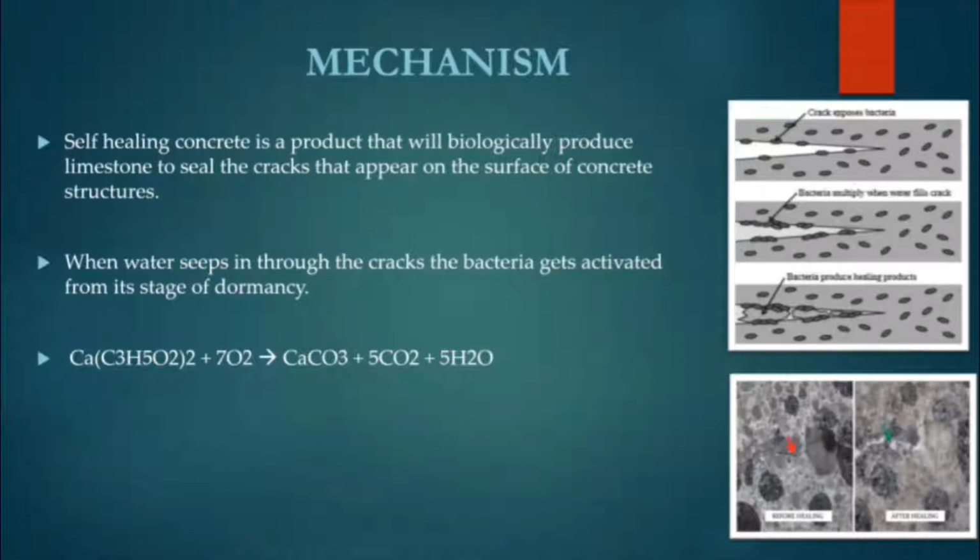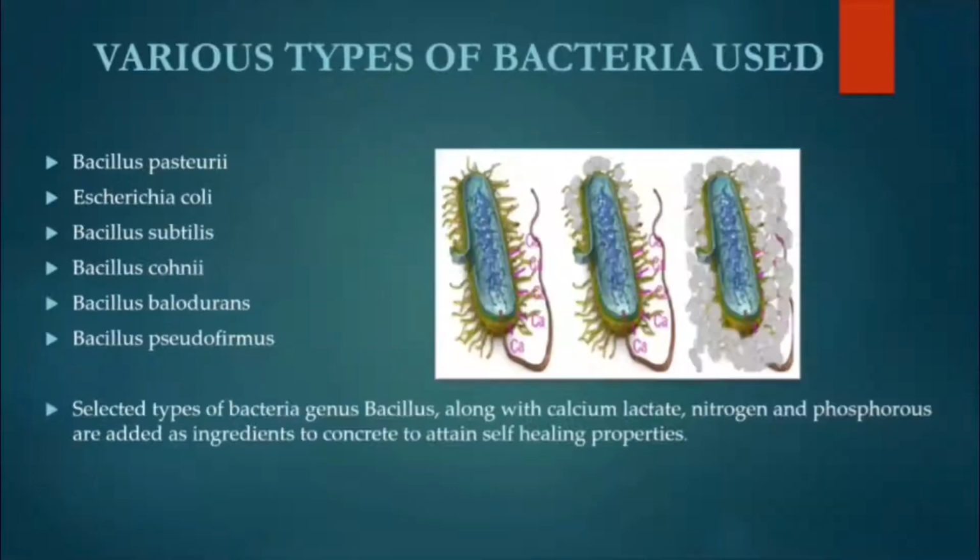The first picture shows the bacterial action on self-healing concrete. At first, cracks will expose the bacteria. The bacteria multiply when the water fills the crack, and then the bacteria produce healing products. The second picture shows the before healing and after healing condition of self-healing concrete.